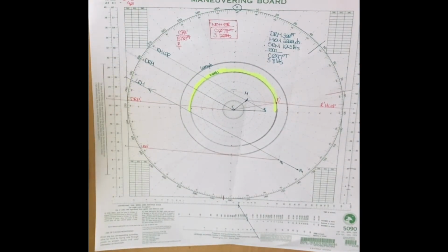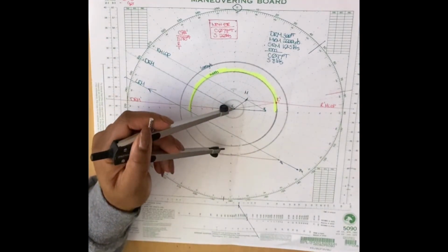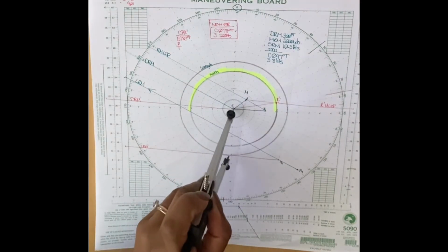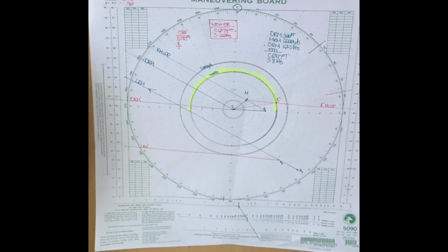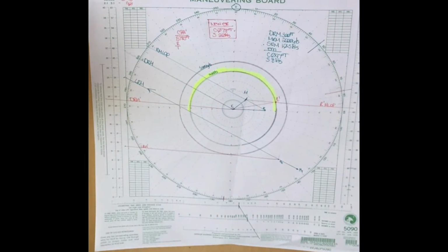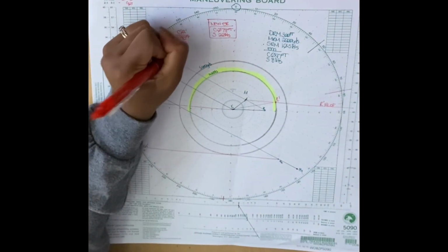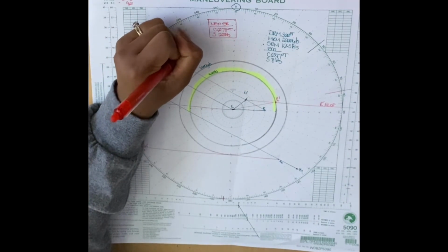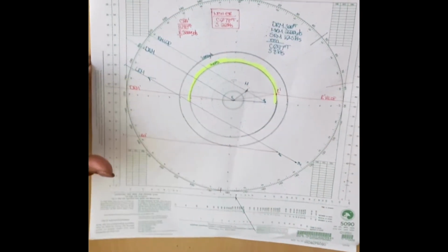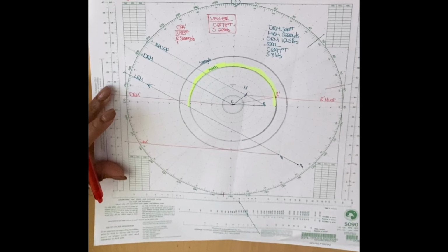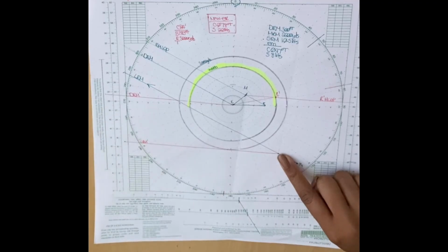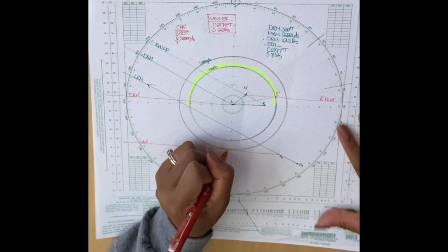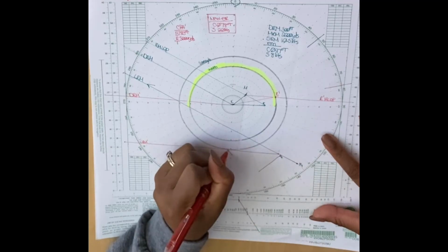Now I need to figure out the range. You can figure out the range one of two ways. You can either just measure from the center, from where your ship is, to the actual point of CPA, which is 5,000 yards, or you can think back to the original problem where the captain told you to open your CPA range up to 5,000 yards. Either way works. Now we want to figure out the time. So we are going to do that by finding the distance from M2 to point of CPA. So that's gonna give us an MRM prime, and I'm gonna go ahead and label that this way.